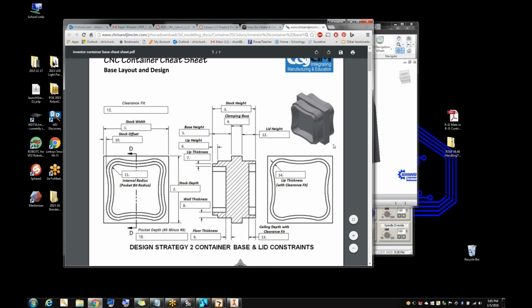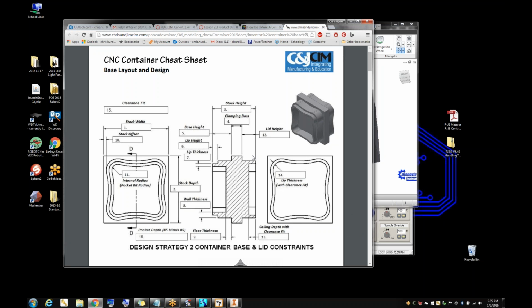Got it. And when you do your designs, you see this clamping boss that's right here. If you make that boss wide enough, you'll be able to design it so that you can machine both sides without coming close to the vise. Okay. Cool. Or you do it the other way, and you do the top out of one piece and the bottom out of the other. You end up with more waste, but you know what? First time around, you don't want to be running into your vise. Maybe you sacrifice a little bit more material the first time.